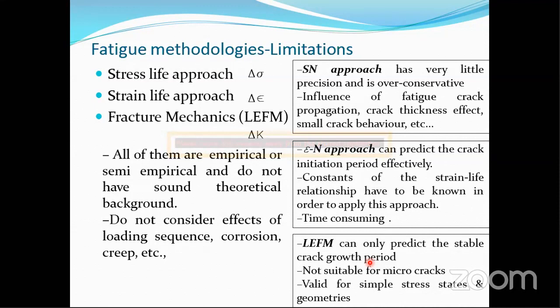We cannot rule out all the cracks to be damaging in nature, because it is only after a certain number of cycles, or only after a certain size of the crack, that they tend to become dangerous. So indirectly, even in the presence of a crack, we are flying the aircraft, or using the components till a certain limit, and we call that the damage tolerant approach. For how many cycles can we tolerate? That is, even though damage is present, we are using that component. That is actually the damage tolerant approach.